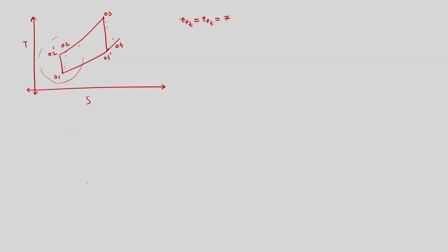So, let us find out. In case when we do not have regenerator, that means that we do not have any pressure loss. Since we do not have pressure loss, this is a simple calculation, since turbine and compressor both will have same pressure ratio, since there is no pressure loss in the regenerator. So, pressure ratio of turbine is equal to pressure ratio of compressor, and that is 7. It does not alter the calculation on compressor side, but it alters the calculation on turbine side.